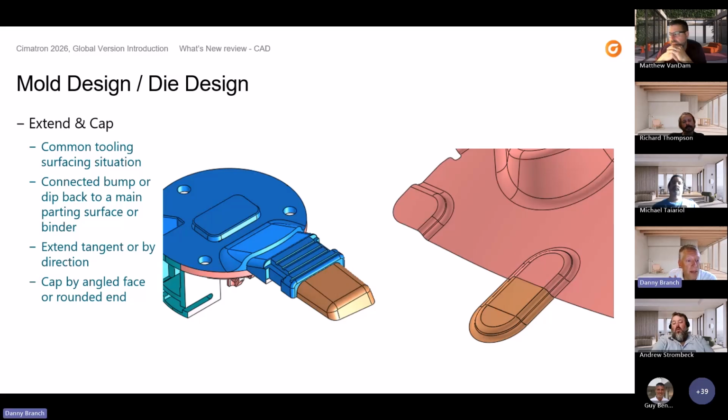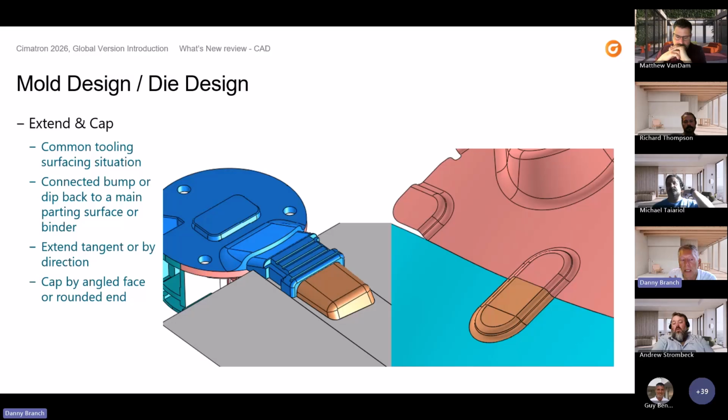What would make it even better is if we could trim to faces underneath. So that's an optional step in here. If base faces exist like these, you can go to the optional step and ask it to trim to them, which isn't easy. Base faces may be 3D, they're falling away, they're rising. It's a challenge. I know of at least one trim case we've identified, which is definitely not going to make the official release, but we will work on it for service pack.